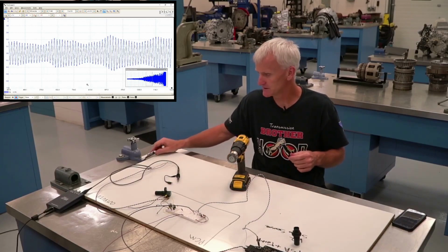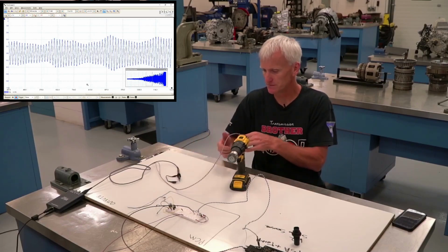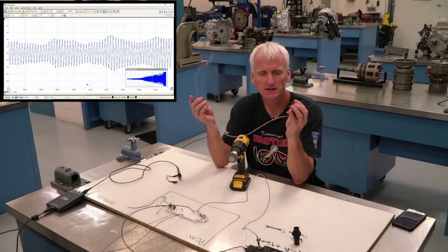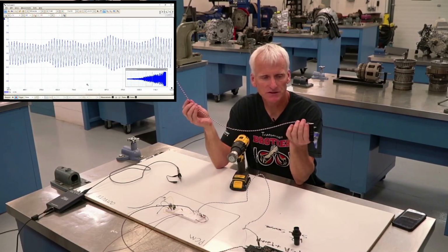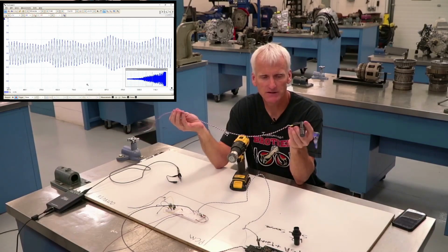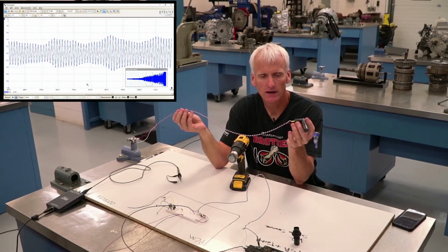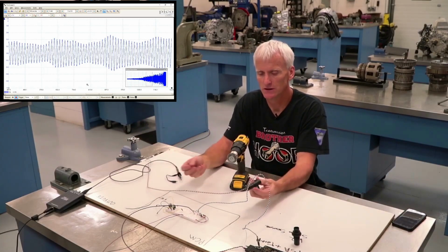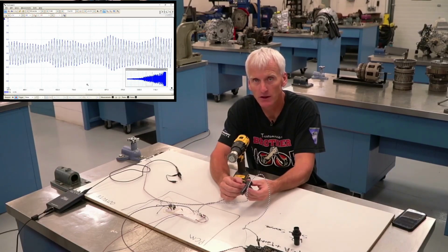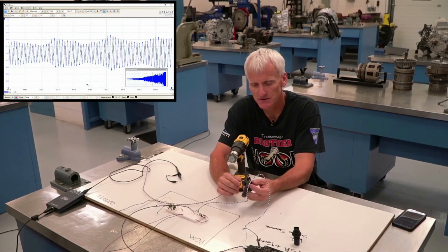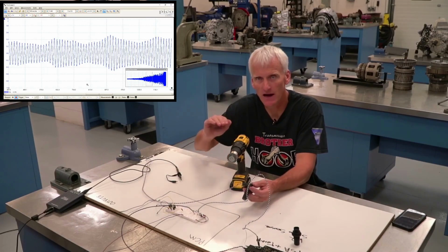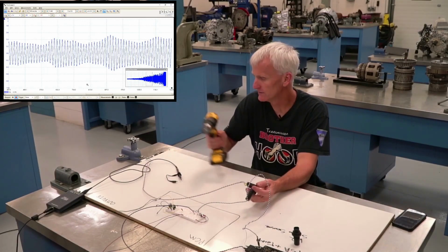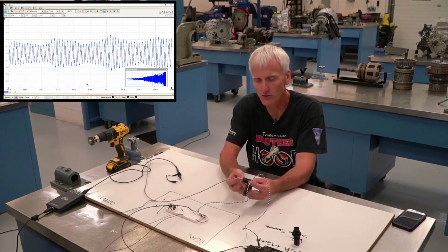There's another type called a Hall effect, and that's what this one is. A Hall effect type speed sensor has 3 wires. It receives power and ground, just like a device would, and then it has a signal wire. There are 2 different types. Usually on the signal wire, you have a voltage applied from the computer, and the Hall element grounds it out. But there are some Hall sensors where, instead of the computer providing the power, the Hall element outputs a 5-volt or 10-volt square wave. This one here grounds out a signal.